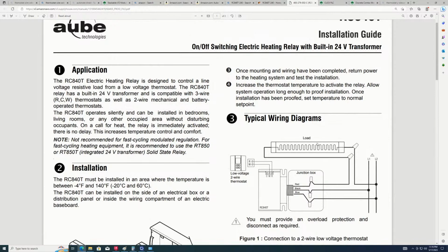Well, you got to remember the load itself, if all of them are going at the same time on the same breaker. No, there's only a maximum of 2 of them on one breaker. Yeah, and I have 4 breakers, so that's a total of 8 amps. Let's round it off to 10 amps. Fair. A 5 wouldn't do it in that situation, but a 10 would have to, because I would be maxing out. I would probably want to put a 10 amp adjustable breaker on there, like an industrial one, so you can tune it in.